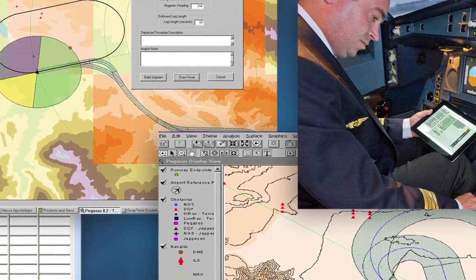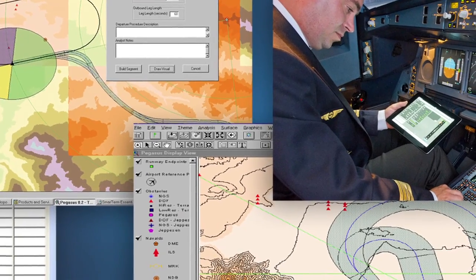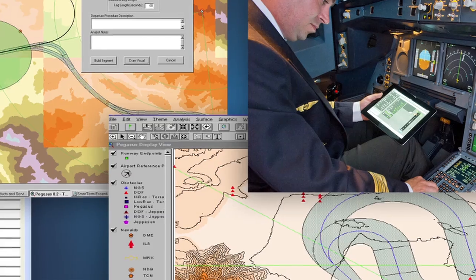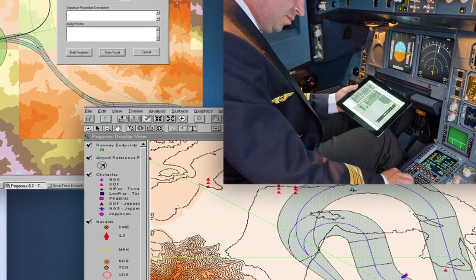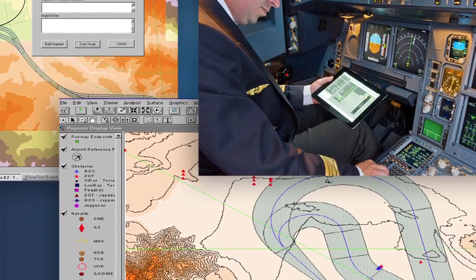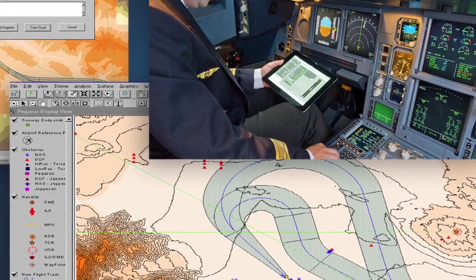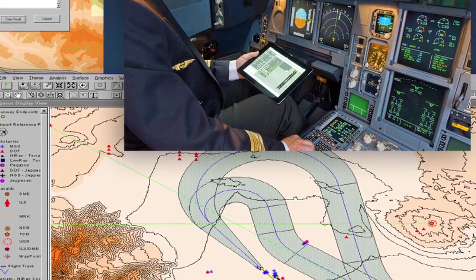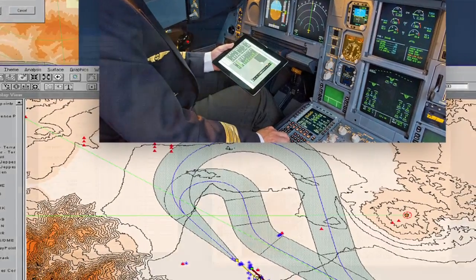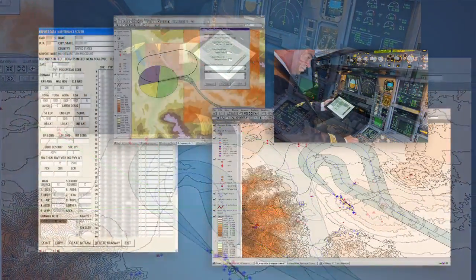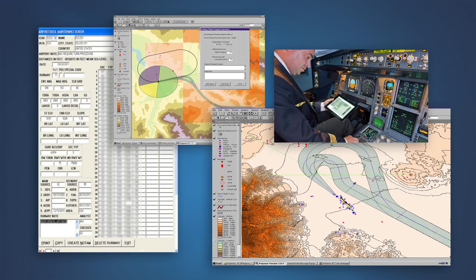Performance engineers will most often use the airplane flight manual data to create a more practical means for pilots to evaluate obstacle clearance to support flight operations. Examples might include a software performance calculation tool, such as might be installed in an electronic flight bag, or a runway-specific airport analysis, summarizing the limitations for departure from a given runway. However, even these tools are dependent on a properly maintained obstacle data set.